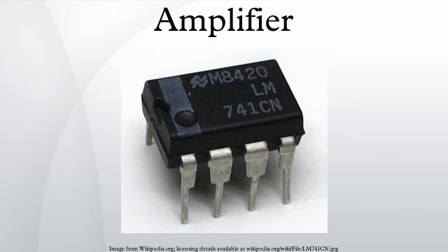A wideband amplifier has a precise amplification factor over a wide frequency range, and is often used to boost signals for relay and communication systems. A narrow band amp amplifies a specific narrow range of frequencies, to the exclusion of other frequencies. An RF amplifier amplifies signals in the radio frequency range of the electromagnetic spectrum, and is often used to increase the sensitivity of a receiver or the output power of a transmitter. An audio amplifier amplifies audio frequencies.